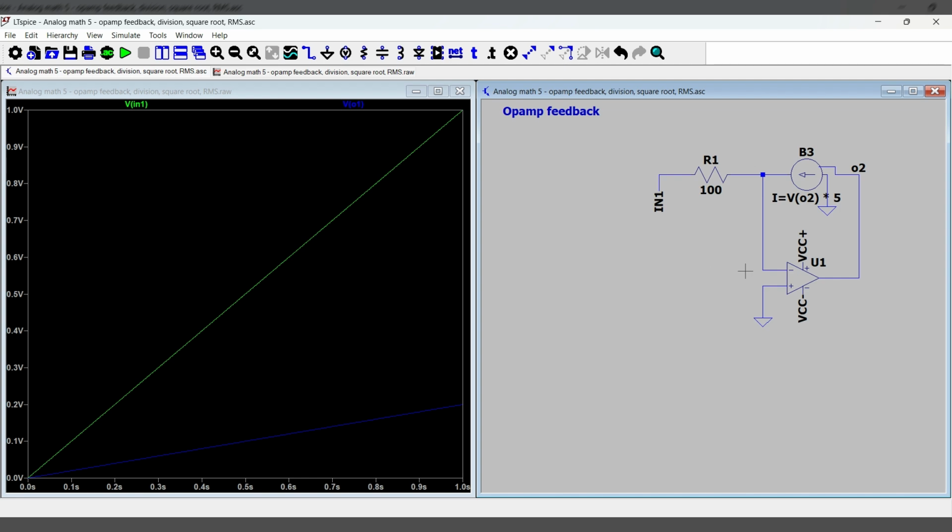So what's actually happening here is that it transforms the voltage, the feedback path, into something that equates the currents. When you have this configuration, the input circuit and the feedback circuit have to produce opposite currents. Because there's no current going through this junction, and because it's grounded at zero, you can set an input current through the input path alone, right? In this case, the resistor will drop whatever input to zero. So it essentially is dividing the input by the resistor value, 100.